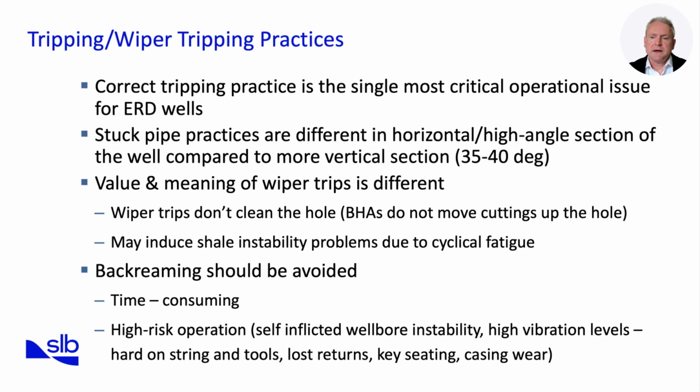Tripping practices take on a new level of importance in extended reach wells. In fact, correct tripping practice is often the single most critical operational issue for ERD. The risk of stuck pipe is much higher in horizontal or high-angle sections than in vertical intervals. A key point is that the meaning of wiper trips is different in ERD.